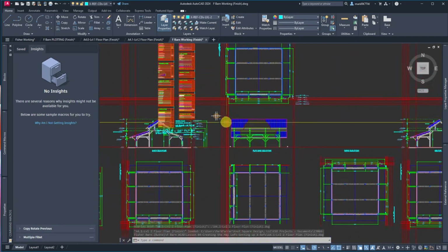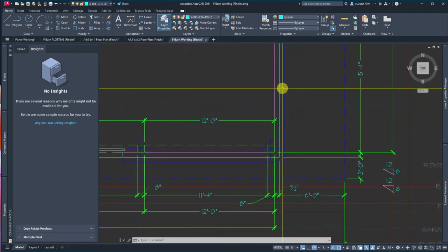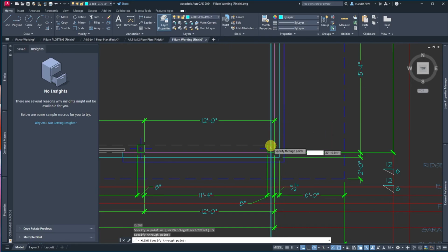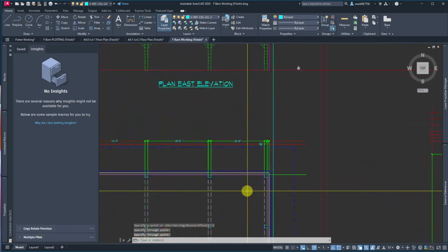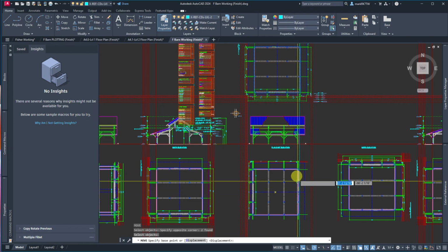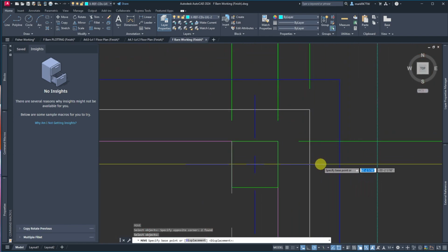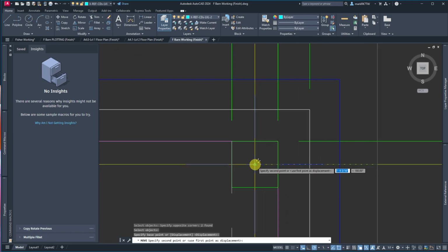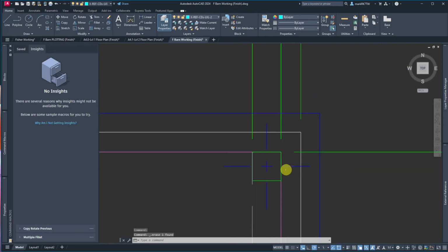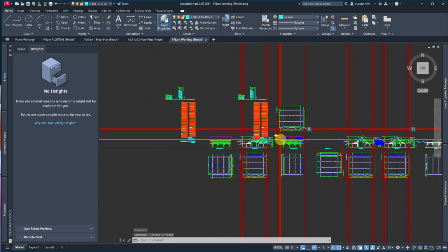Looks like it didn't, but I've got to check. XL vertical. Let's put it right on that crosshair. And it's a blue line, so it's going to stick out. So yeah, it didn't land correct. This is lined up with this, so I need to move this one. So we're going to move that, and we have that X line. I'm going to take and bring this cord out to here, and then pull it back to here. Then I can delete this. So now that's lined up. So now let's X-clip it.